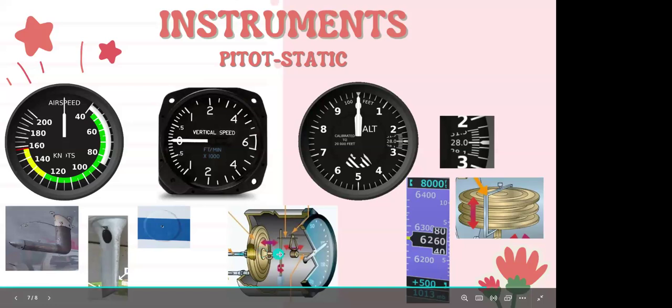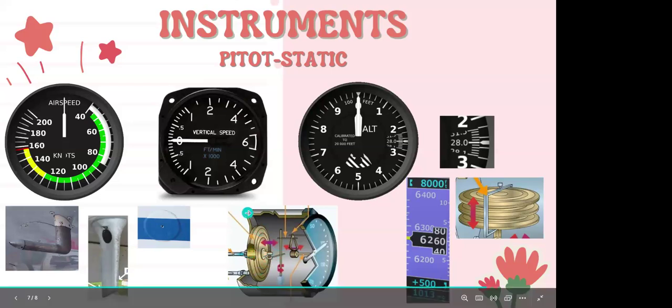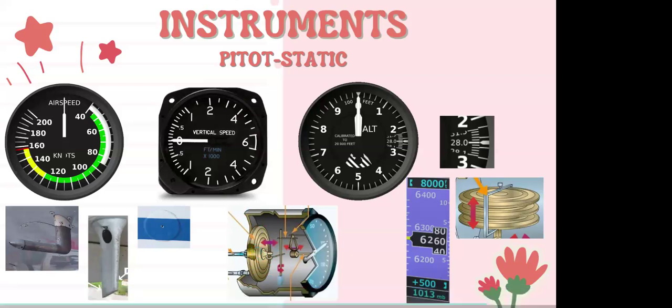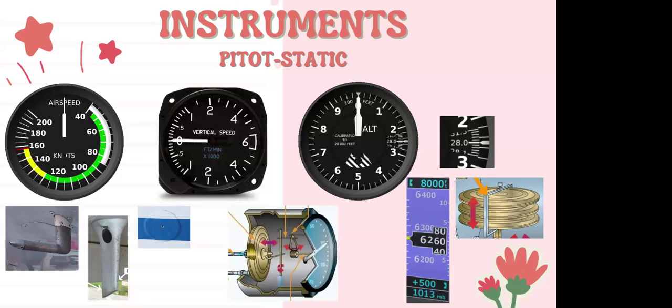This also happens when we go faster. If we're moving objectively faster through the air, we have a stronger air pressure inside of the diaphragm, causing it to expand, which causes it to show a higher airspeed reading on the airspeed indicator. Vice versa, if you slow down, you have less air pressure inside of that diaphragm. Makes sense. We're not moving as quickly, not as much air is entering through that pitot tube, molecule-wise, which is going to cause a lower reading on the airspeed indicator.